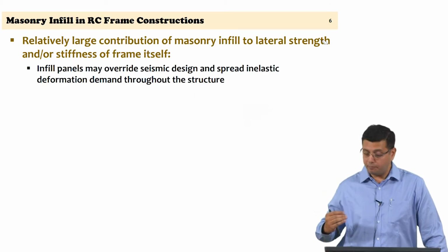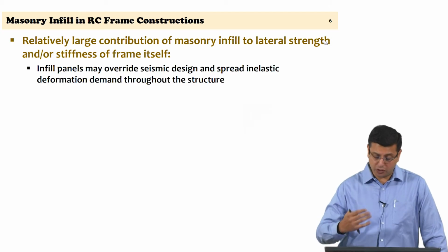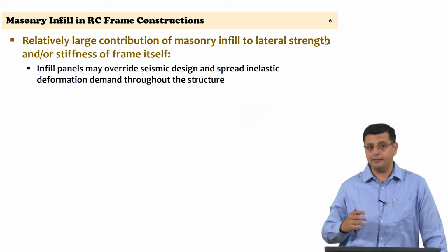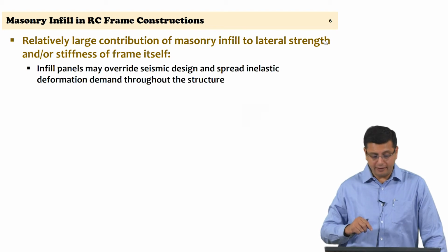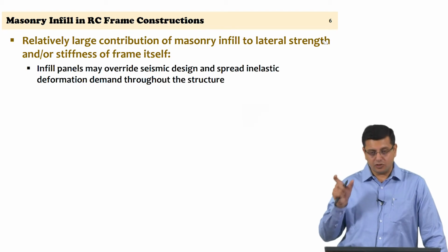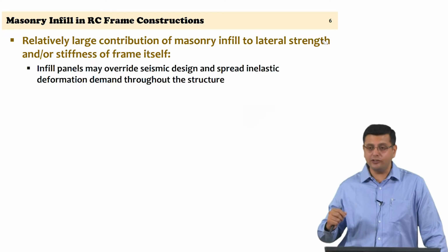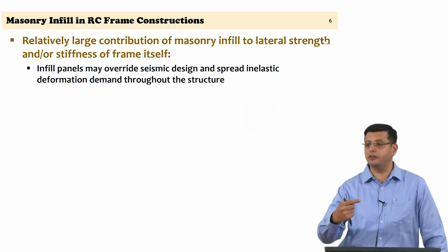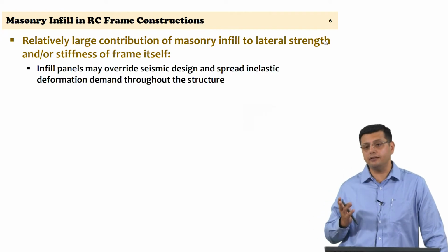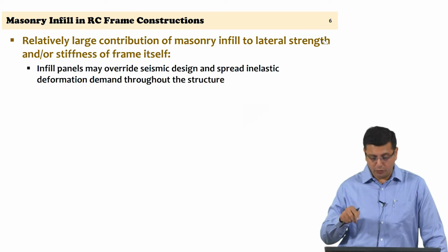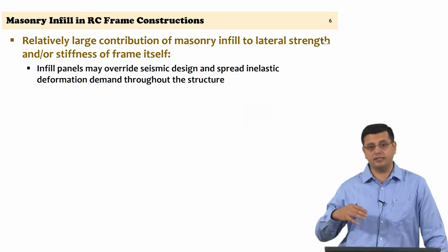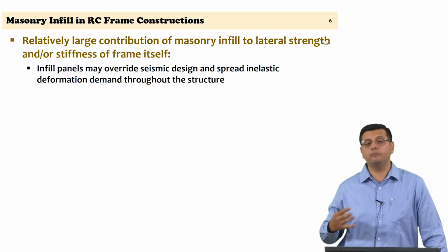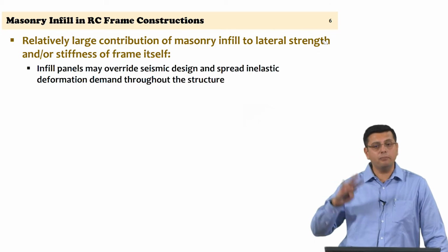The reinforced concrete moment resisting frame could be designed seismically, but if the additional effect of interaction is not considered, then these strong panels would lead to a condition where the demand on the reinforced concrete frame is higher than what was expected as a bare frame, and you will have inelastic deformation that will start spreading throughout the structure, which was not expected because your modeling and analysis was based on a bare frame.